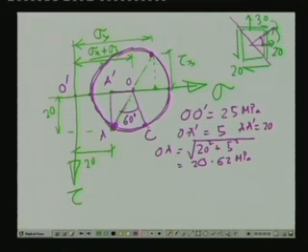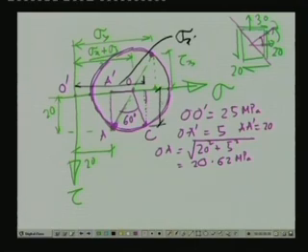Now, we are interested to find out the stress at this particular plane. So, if we drop a perpendicular to the sigma axis, this will give us the value of sigma x on this plane. That is the value of normal stress. Let us call that as sigma x dashed, if we call this as x dashed plane, and this magnitude will give us tau x dash y dash.